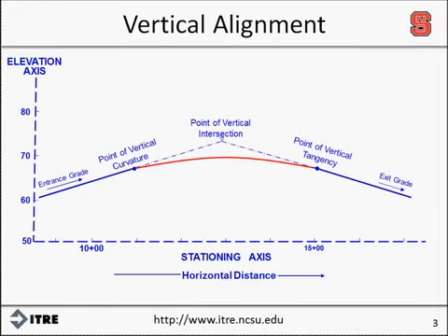In the vertical perspective, a roadway is also comprised of tangents, which are smoothly connected by curves. For vertical alignment, the tangents represent grades, which can either be flat, uphill, or downhill. The typical vertical curve is a symmetric parabolic curve whose shape is defined by the parabolic equation. The information required to fully define a vertical curve is the elevation of the beginning of the curve, the grades of the two tangents that are connected, and the length of the curve. The naming convention of vertical alignment is similar to horizontal alignment.